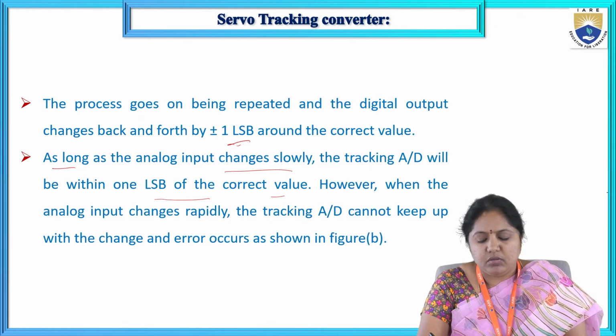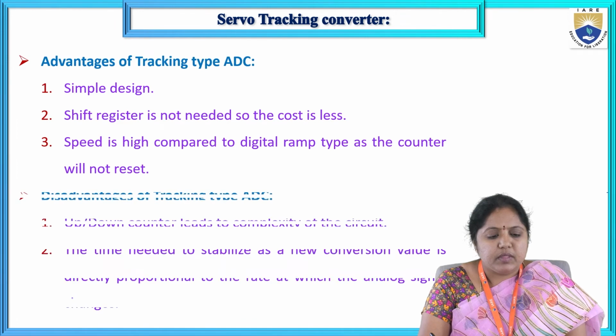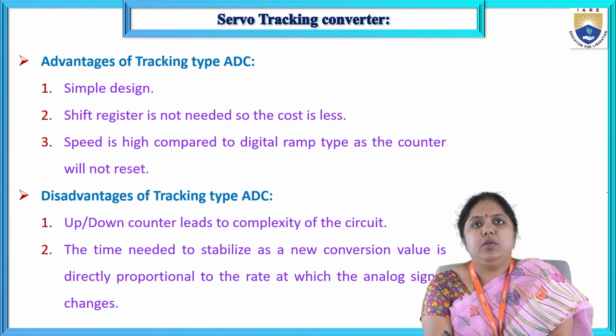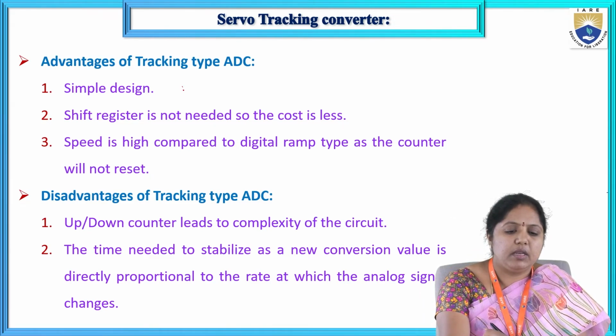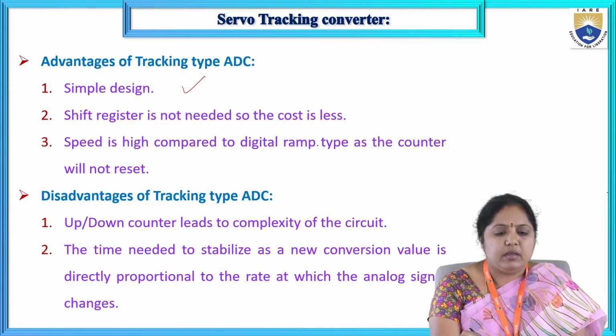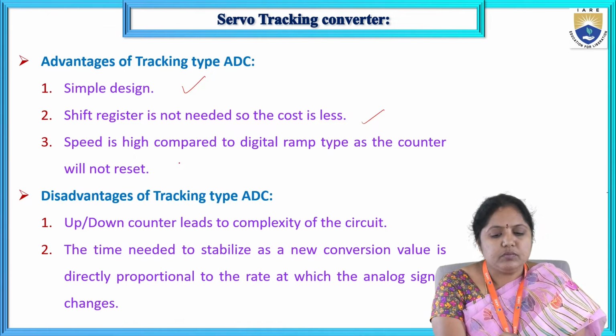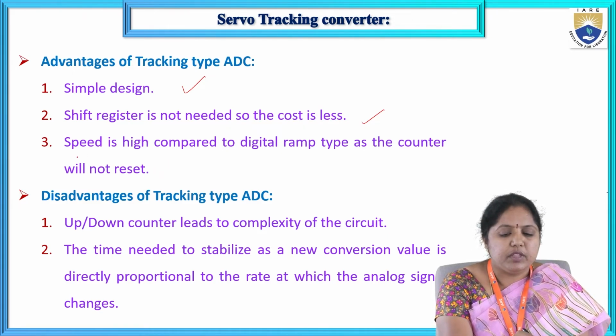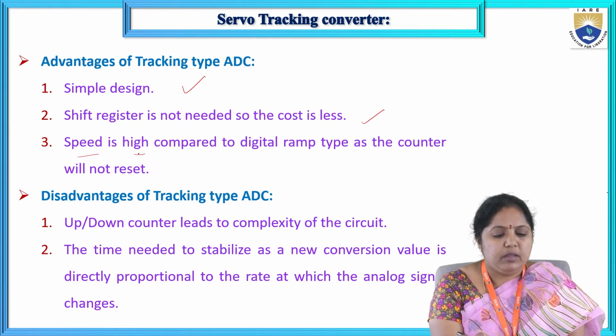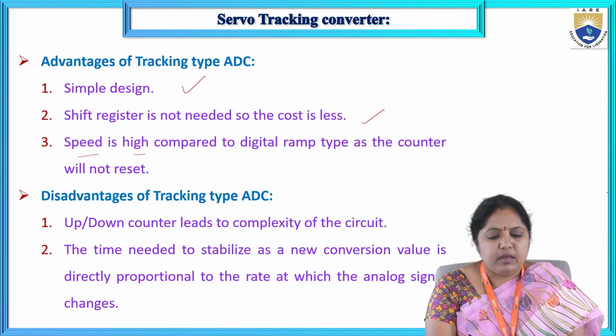Here also, while doing the conversion process, it will take a lot of time, but the design is simple, and shift registers are not needed for this one. Compared to the previous model, the counter type of ADC, the speed is high for this one.